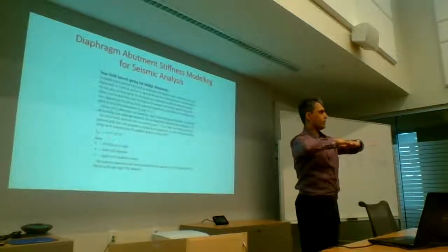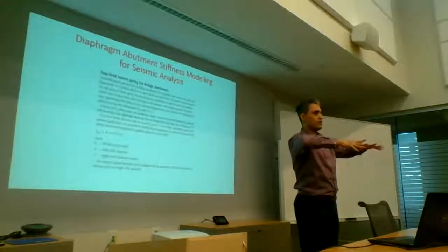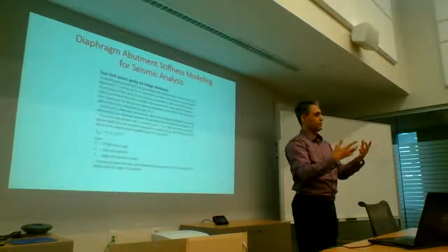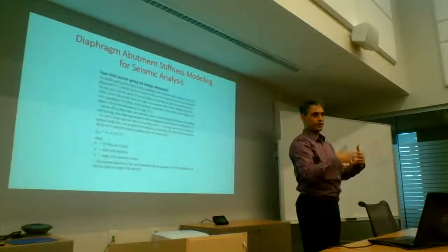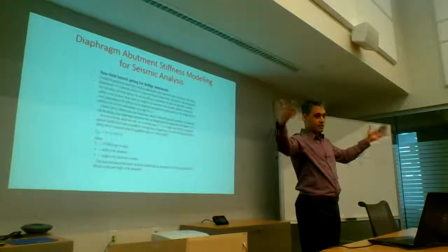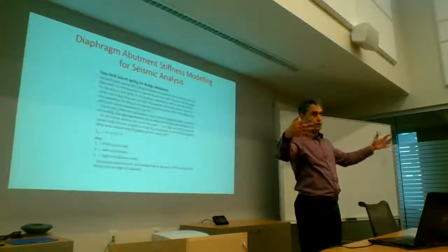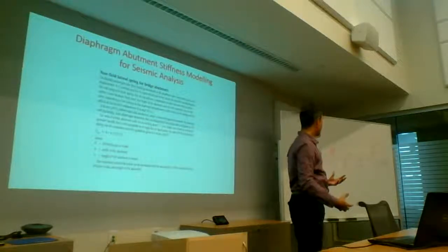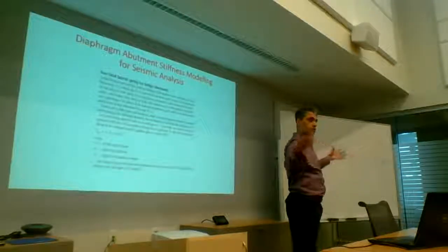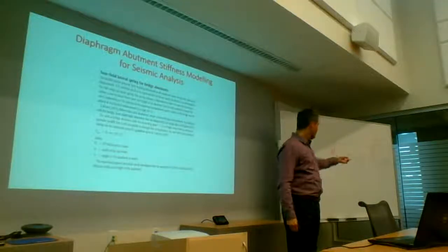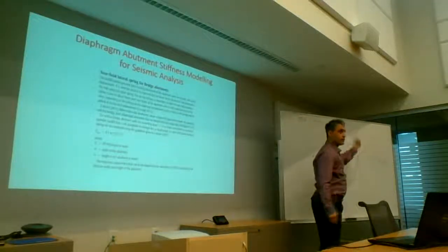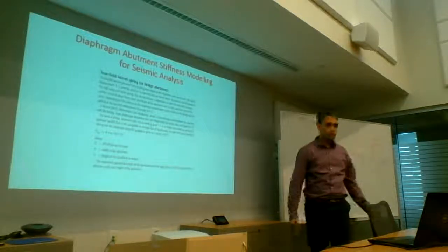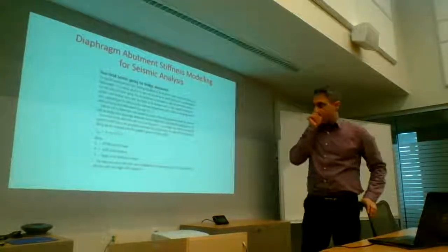But guess what? Now it can't just open up at the joints. It won't throw load into your piers at all, or very little, below the threshold that they can take. So the load is going to the abutments. The trick is, can you make them that stiff and strong that they won't fail? And if you can, and we've done it successfully on many projects, it's a really good opportunity to get away from mucking around in here. There may be traffic underneath, there may be lots of issues. You can get away from it.